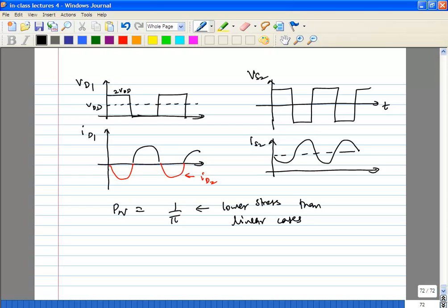So in a real case, this may not be very applicable to high frequency PAs. Class D is used quite often in, for example, audio amplifiers, but in RF power amplifiers, it may not be that useful. What is more useful are the class E and class F architectures.